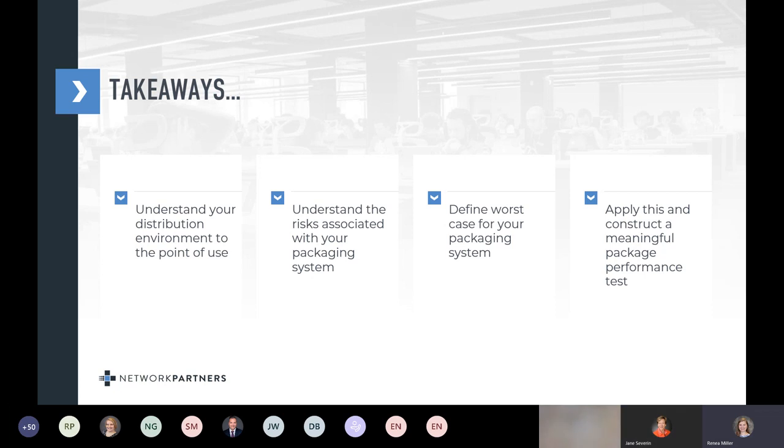But do you suggest peel open and seal transfer visual inspection after other package tests? Do you include seal width measurement? Yes, I would include seal width measurement. It's important to set your acceptance criteria for minimum seal width and include that in your evaluation.